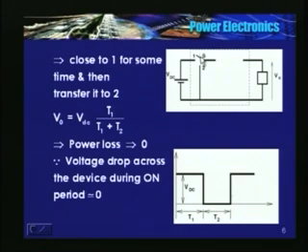Since this active device, the switch, is operated in saturation, power loss across it is approximately 0. Okay. So thereby increasing the efficiency.